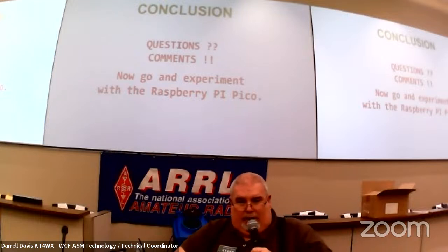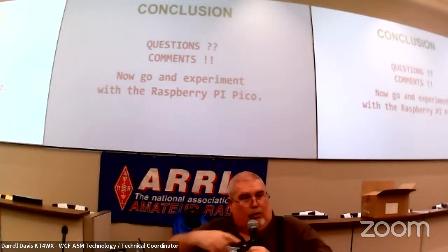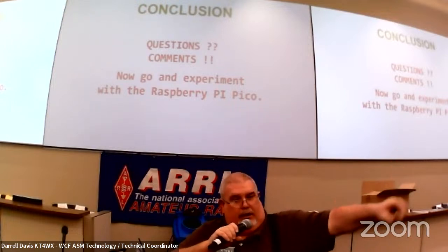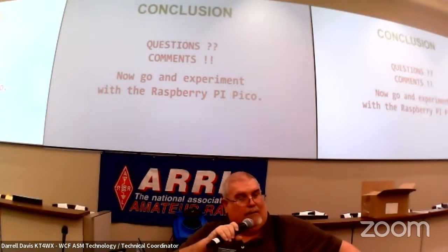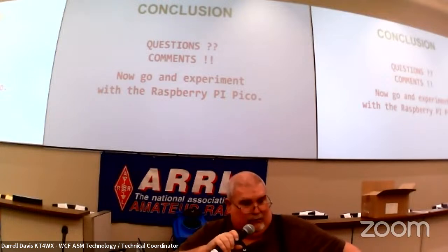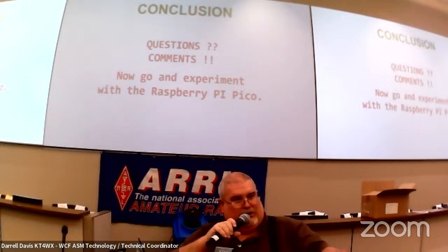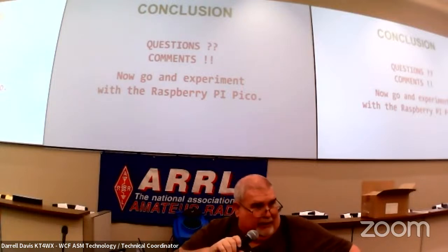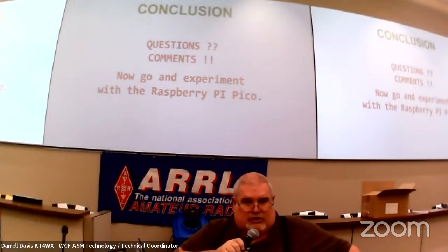So if you need something to gather data, like a weather station, you should be able to build a weather station that passes data to the outside world with that. It's only pulling data from a few sensors every few seconds. There's plenty of horsepower in that. You could make it run a basic OLED screen. You could use that Pi Pico, I would imagine, to control QRP transceivers. If all you're doing is moving the frequency and need a display, it would have more than plenty enough horsepower to run a simple QRP radio or something you want to homebrew. That's where it has an advantage.